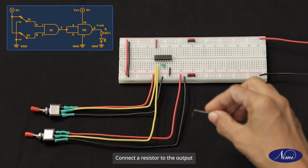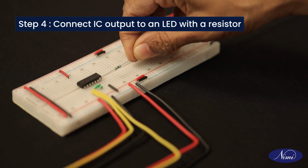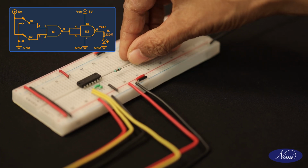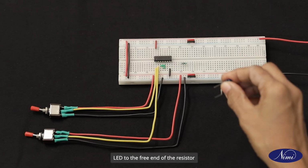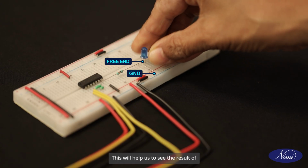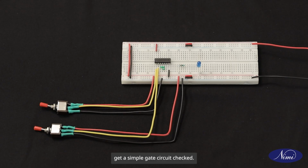Now, let us set up our visual indicator. Connect a resistor to the output pin number 6 of the IC. This will limit the current to the LED, protecting it from burning out. Then, attach the anode of the LED to the free end of the resistor and cathode to the ground. This will help us see the result of our AND gate's output clearly.